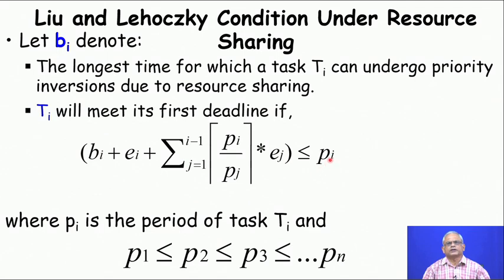Okay, deadline is equal to the period. Now, when the tasks share resources, we need to just add this term here, B_i, and B_i is the total blocking time for a task on account of the lower priority tasks. So, once we develop the 3 tables for 3 different types of inversion, when priority ceiling protocol is used, we determine the highest entry corresponding to that task and use that value here, and then determine whether the task set can be schedulable.